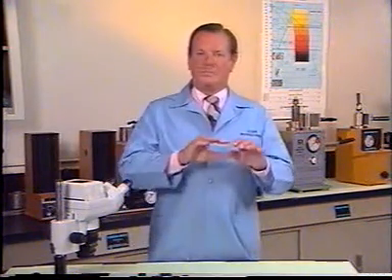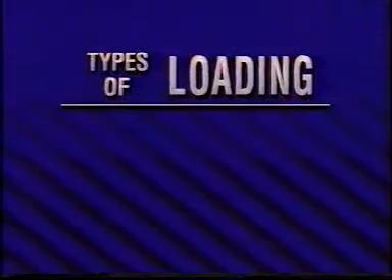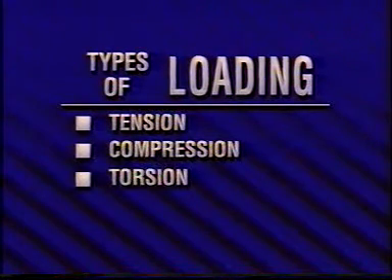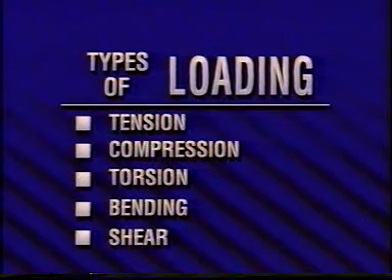For now, it may be more important to visualize the distribution of stresses through the material that leads to fracture. To understand and visualize the distribution of stresses applied to a part, we must first determine the type of loading on the part. A part can be loaded in tension, compression, torsion, bending, gross macroscopic shear, or any combination of these. In tension, the member is simply pulled.